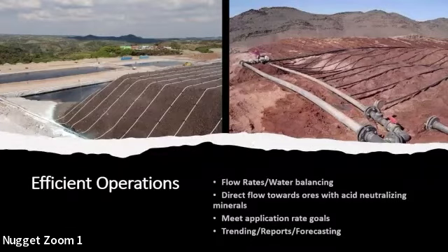At a PSD indicator of 4 or greater, and by the way this correlation is just for first lift conditions, the ore should be sufficiently permeable, but below 4, you may have permeability issues under first lift conditions.